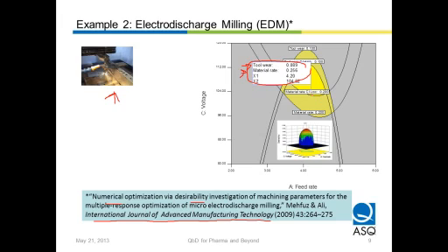But of course, we have to realize that we're not going to be able to operate this machining or milling operation right at this point all the time, and so it would be good if we gave ourselves some space. So they developed some specifications on material rate and on tool wear, and these created a window, which is the sweet spot. And then inside of this window are superimposed confidence intervals to provide a more conservative region that we hope to stay within, and then have very little chance of the process ever going out of control.